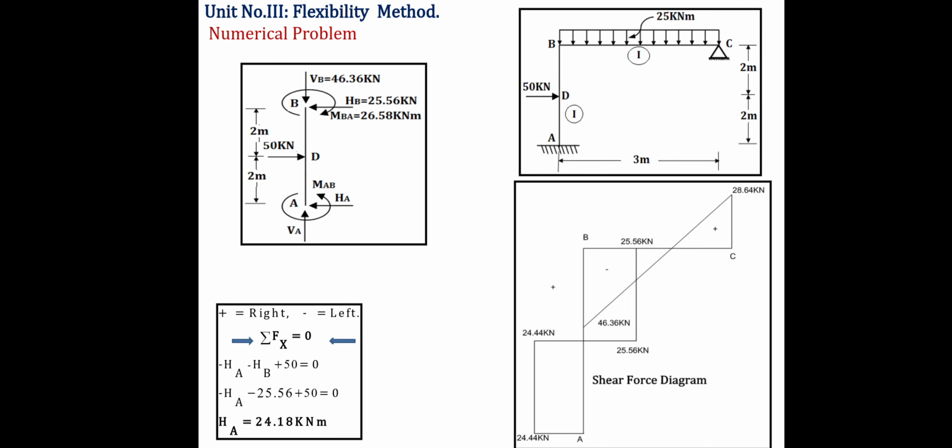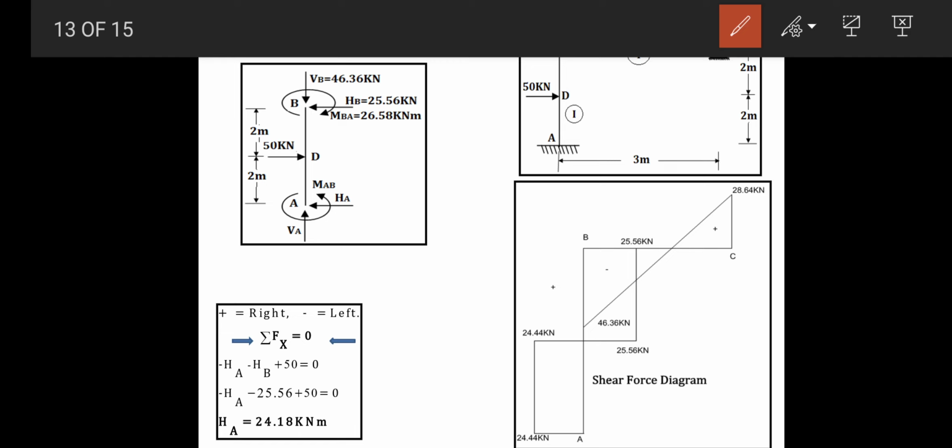Now before drawing the shear force diagram, let's calculate HA. To calculate HA, let's consider the summation of forces, toward the right positive and toward the left negative.